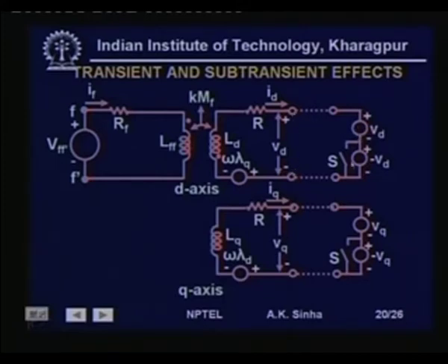The terminal voltage is Vd. When we open this switch, then these two voltage sources are in series and the voltage across these terminals becomes 0, which indicates a short circuit condition. So, in order to create the short circuit condition, what we are seeing is that the changes are produced by applying this minus Vd voltage source across the terminals. That is, we can use the superposition principle, whereby we can have the voltages created by each voltage source separately, and we can see this condition.